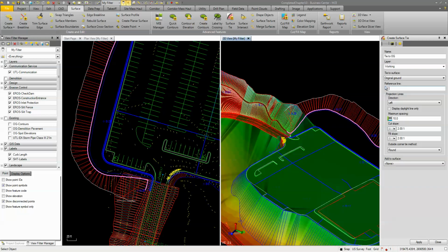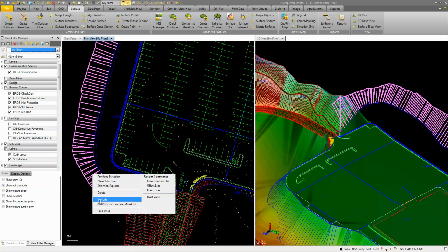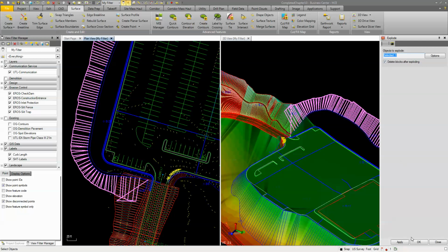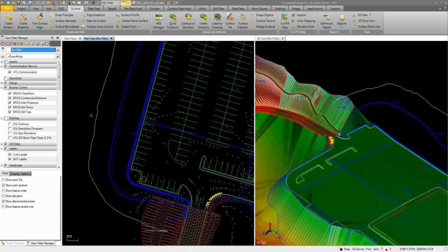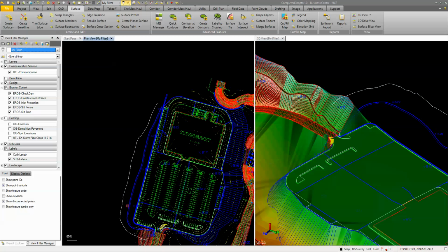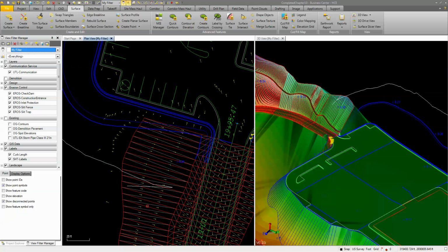Okay. So I'm going to do the same thing. I'm going to pick this. Let's close this. I'm going to pick this. I'm going to right click, explode. Click OK. Everything's still selected, so I'm just going to control and deselect that tie, and then I can just click delete, and then we'll get rid of this as well. Okay. So kind of another quick way of doing it, nice little tip. Everything stays selected, so I can just delete it. So it's kind of like a select previous.